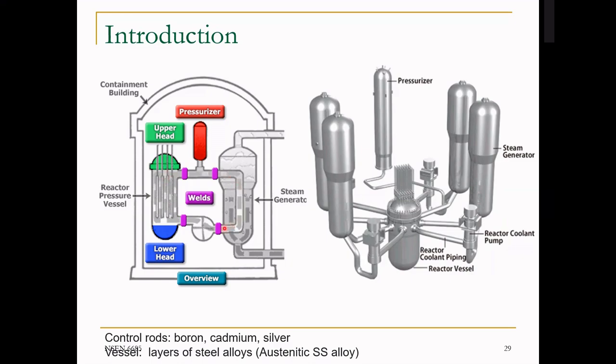Primary loop. And there's a pump. There is a pressurizer. So we are focused here on the pressurized water reactor. Then this is a steam generator, where the energy coming from the fission reaction is going to be exchanged, and that steam generator is simply a heat exchanger, to convert liquid into steam. So this is a picture of the real system here. This is the reactor vessel, which we simplified by this. Upper header, lower plenum, and the fuel is stacked inside.